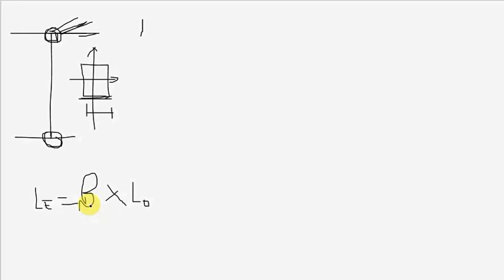There's something called the slenderness ratio. How do you find it? The aim is to know whether our column is slender or a short column. So the next thing after finding the effective length, let us say the effective length for a column is 3 meters, we need to find what is called the slenderness ratio.